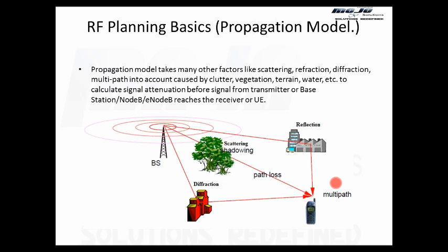If it is a destructive interference, then destructive summation, the signal will fade. So it can fade, it can enhance itself. Usually the effect is 3 to 6 dB because of multipath in the propagation model, and the propagation model has to predict it more accurately.